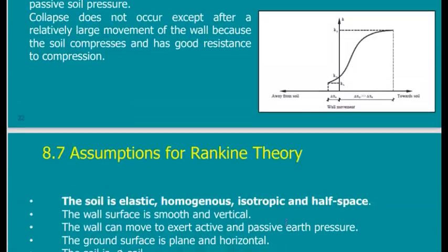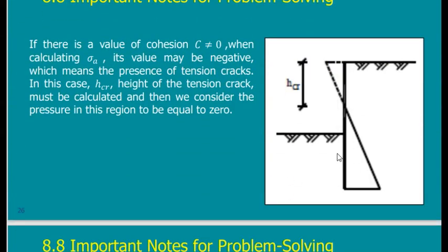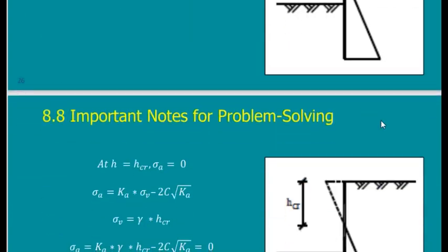a triangle. I will just go to the figure here. This is the crack, and this is where the earth pressure will start. But from this point to this point, I should add here a triangle showing the pressure of water. This is important, because it is not that I'm neglecting the earth pressure. No, I'm neglecting the earth pressure and replacing it with a triangle for water.